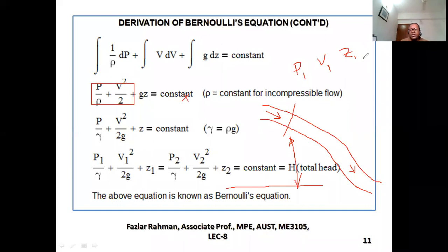Now, I would like to know how much the pressure is over here, how we can figure it out. We can put a pressure gauge, then you can figure it out, right? But I don't want to use the pressure gauge. I look at the drawing, I know the diameter of the pipe over here, say D2. I look in the drawing, I see the diameter of the pipe over here, D1. Now, right over here, I have some equipment or pressure gauge, I read the pressure, that much. The velocity of the fluid I'm getting from the pitot tube is this much, vertical elevation I know. These three terms I know. But I need to know what will be the pressure over here instead of putting in any equipment. Say you have a distance of 10 miles from the first point to the second point. Now, how can we figure it out?